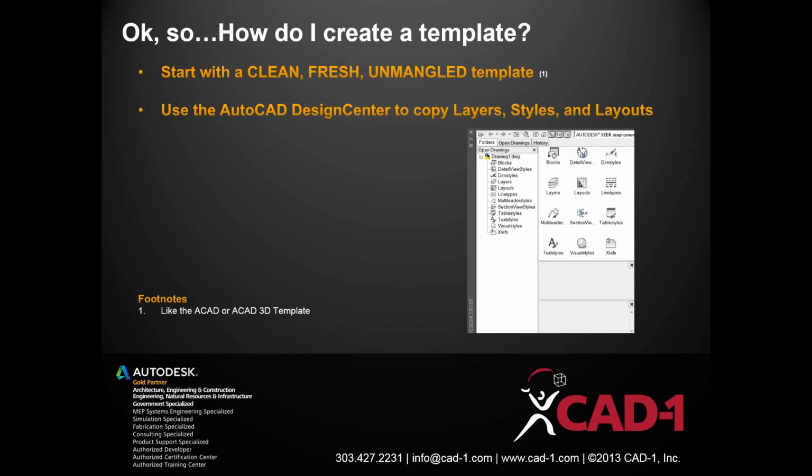The AutoCAD Design Center. And as you see there, I can copy block definitions, dimension styles, layers, layouts, line types, multi-leader styles, text styles, all the stuff that you want to plug into a template. Okay, what about my settings, Warren? Aren't those in there? No. You're going to have to manually edit the settings. Oh, darn, some typing. What about my units? No. You're going to have to manually change your units. So there is going to be some manual work.